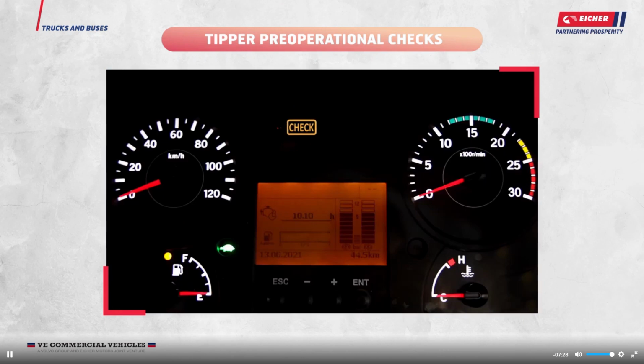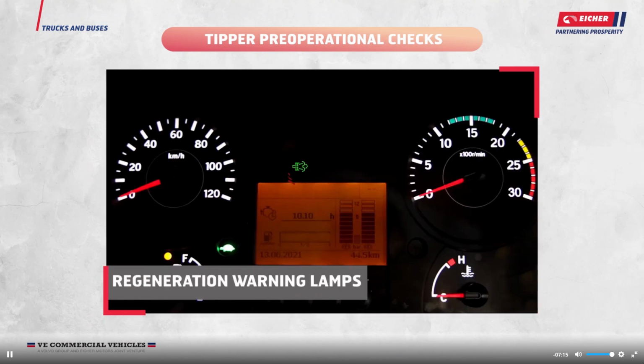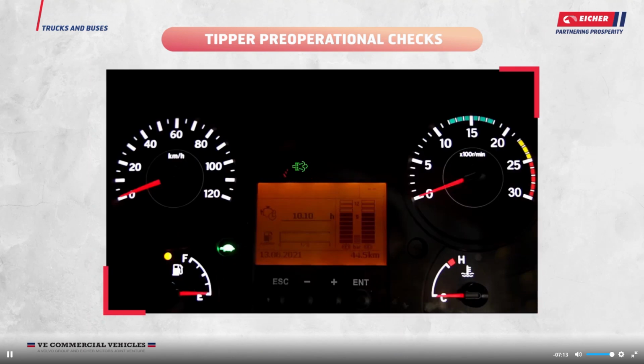Check engine warning lamp, MIL lamp, AdBlue warning lamp and ABS warning lamp. If warning lamps are continuously on, get system checked and repaired at EICHER authorized service center. Check the regeneration warning lamps status.